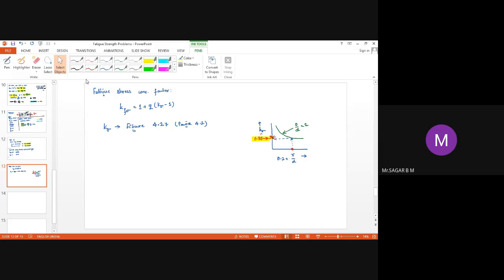It says combined stress concentration; look at the combined stress concentration. This is 1.35. So basically, you remember one thing: between 4.21 and 4.27 there is a very subtle difference. What is the difference? We use 4.27 when there is combined loading, when there is a combination of 2 or more types of loads. 4.21A will be used only when there is a single type of load acting on the component. In this problem, there is a single type of load, only bending load.